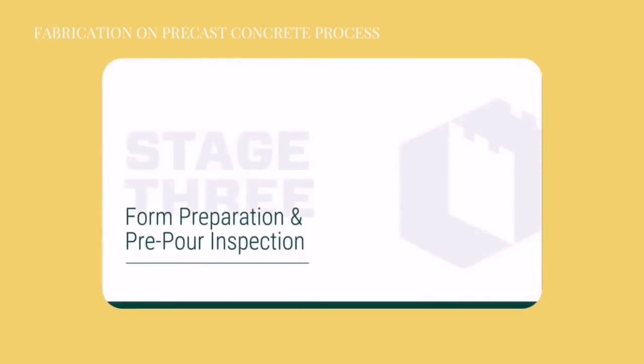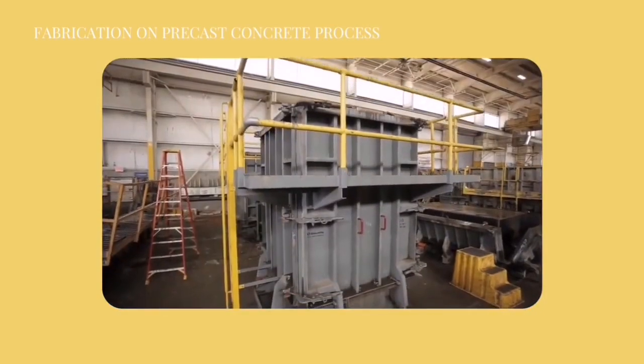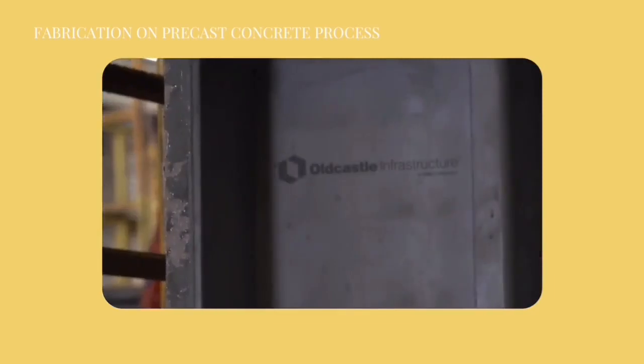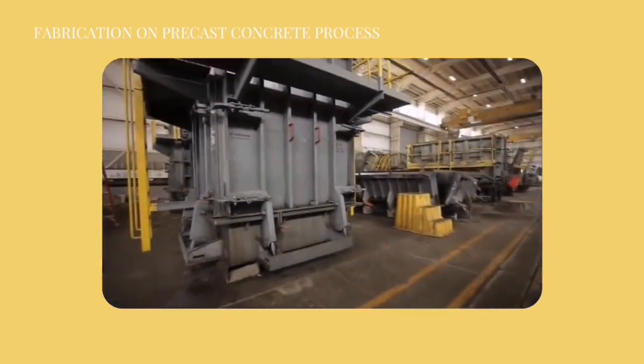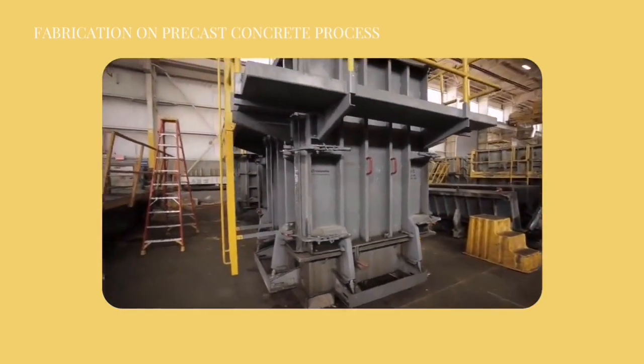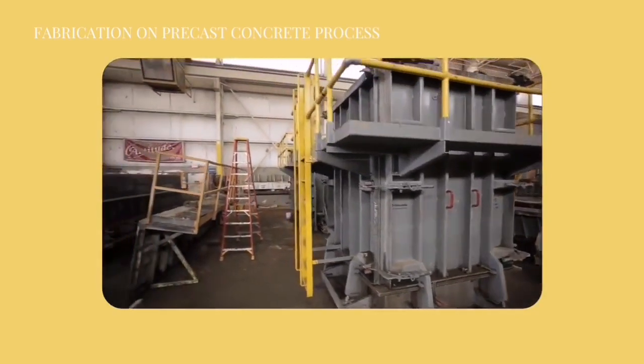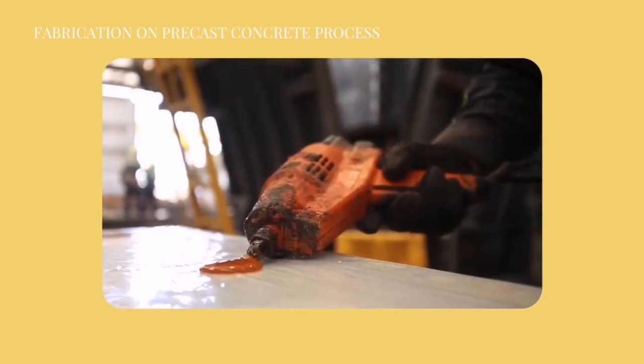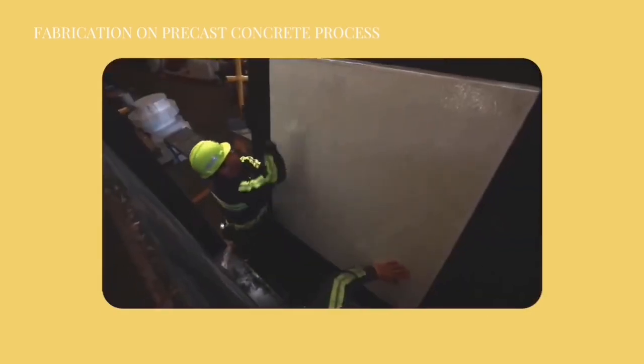Once the cage assembly is complete, we can begin to prepare and clean the form. Oldcastle Infrastructure uses a variety of steel forms, which are built to last and will maintain exacting tolerances for more than 30 years. At this point, all openings, cutouts, or embedded items are secured to the form.